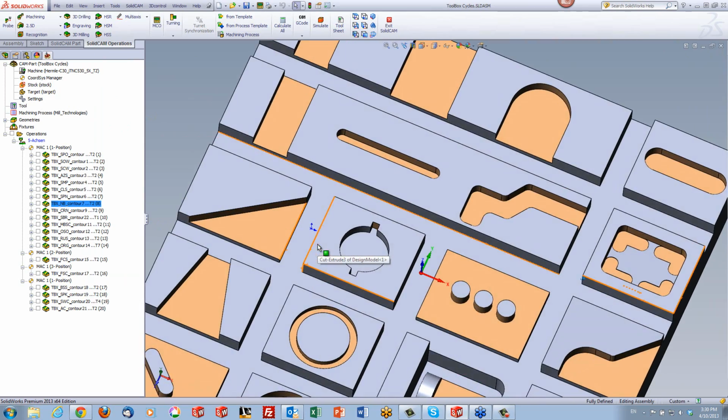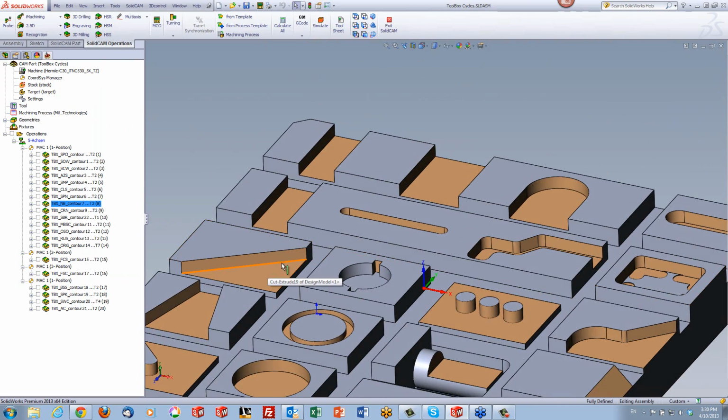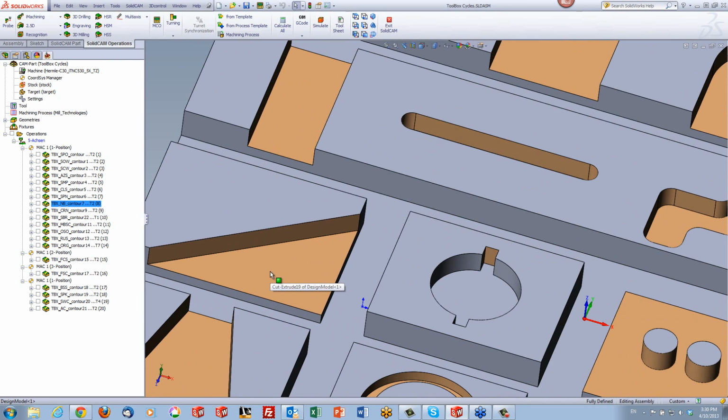Another one we have here that's very useful is actual cornering, where I have a corner that I want to clean. We used to use a profile operation, and what happened in the profile operation, in order to do this edge, I would actually create just that one geometry. And if I do a clear offset, it'll actually do parallel cuts to it, but do a lot of air cuts on the edges, which is not necessary. Another way to do this was also doing a pocket, creating a pocket over there and working in a pocket area only. But sometimes you had to decide how much of an offset I want to give at the edges over there. Different ways of doing it.